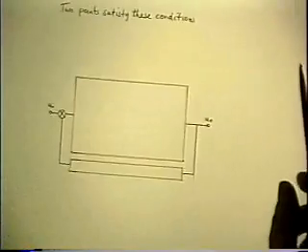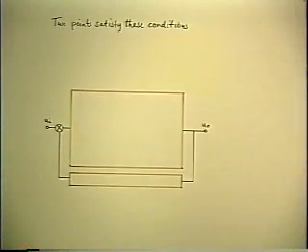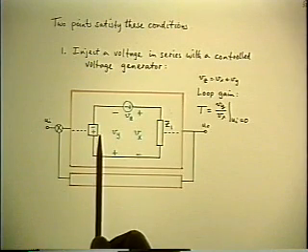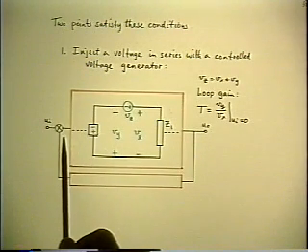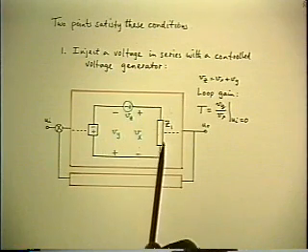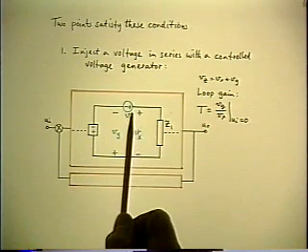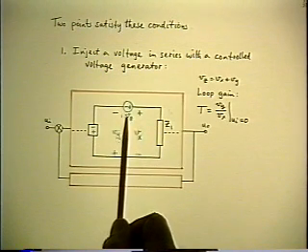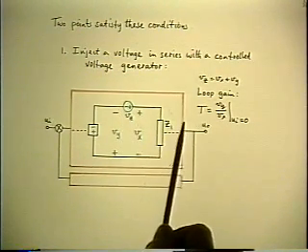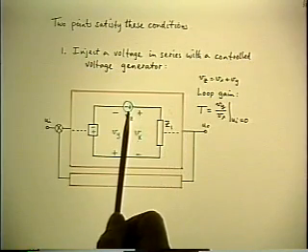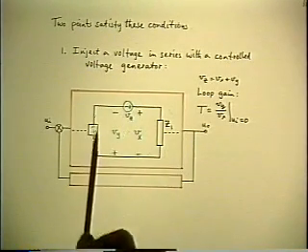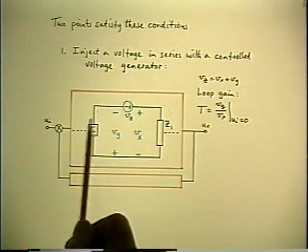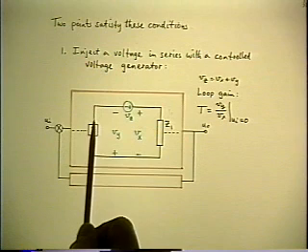One condition is if you can find somewhere inside the forward loop an ideal voltage generator dependent on some earlier signal feeding into some internal load Z1, this is a point where you could do series voltage injection. This satisfies the two conditions. It's inside the loop, and by injecting the test signal, you don't change the value of this generator. That is, you don't change the output of the box in front of that.